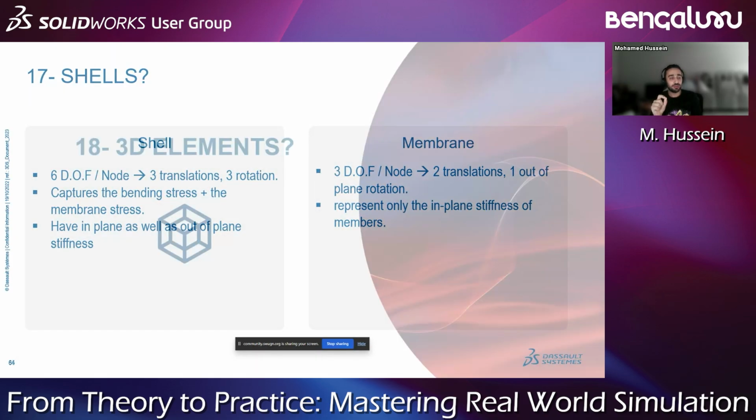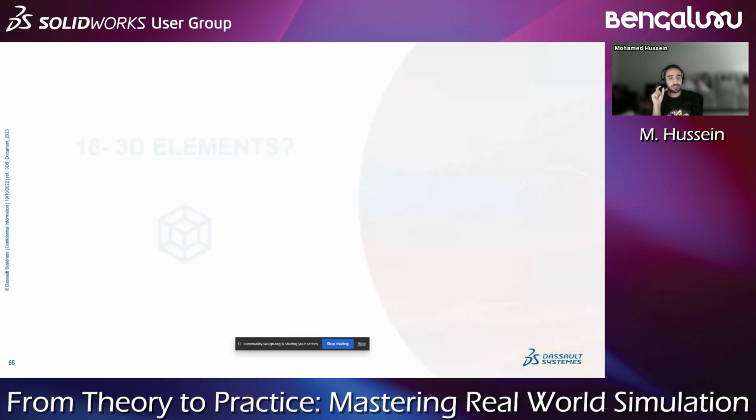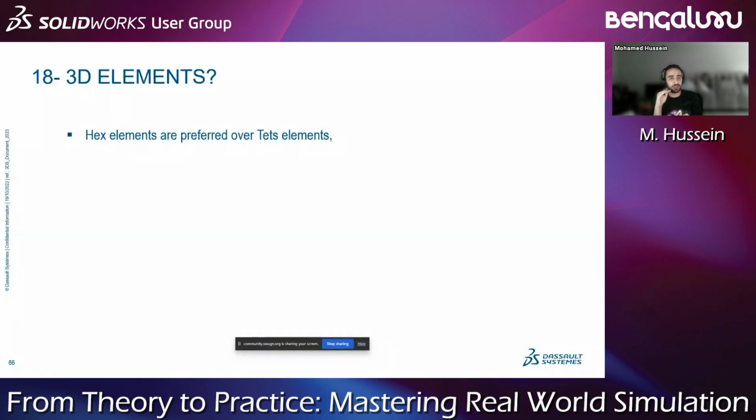When you fail to choose one of the previous elements, you go to the 3D elements. So 3D elements are never my first choice. Hex elements are always preferred over tetrahedral elements.